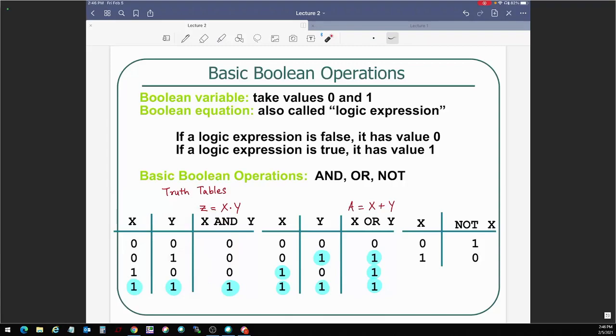Meaning, we talked about the fact that 0 is actually not 0 and 1 is not actually a 1. It's actually representative of a range of voltages, right? So when you are trying to put in more and more inputs into a logic gate, you are kind of risking the voltages to be not representative of 0 or 1 the way you would want them to. So that's called fan-in limit. And every logic gate will have a fan-in limit. In fact, it'll have a fan-out limit as well. More about that as we progress through this digital circuits lecture.